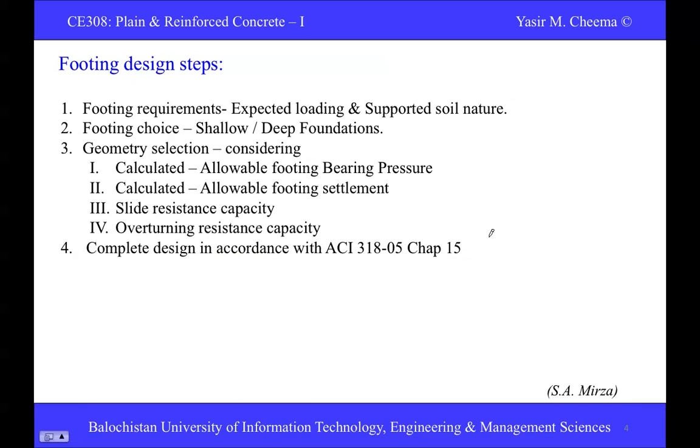Now, some different design steps for footing. Basically, first of all, you must know the footing requirements. Footing requirements mean the expected loadings and what kind of soil structure is available where you are going to design the footing. These are two important things to know before we go on to the footing design: the nature of loads, the values of the loadings, and then the soil structure there. Further, you can decide which footing you are going to design.